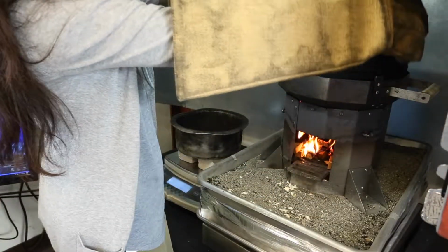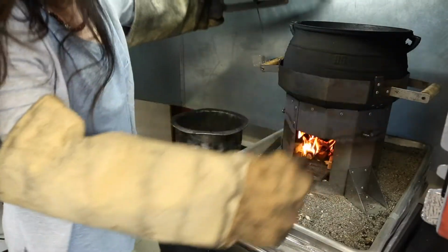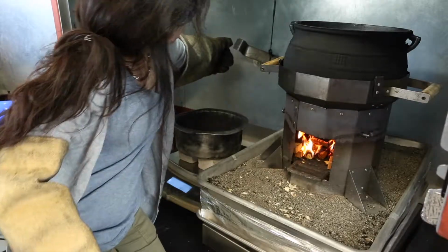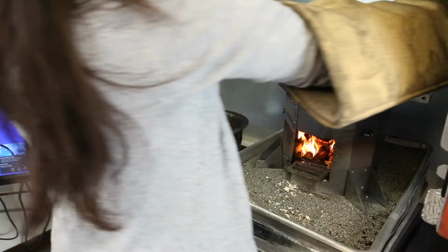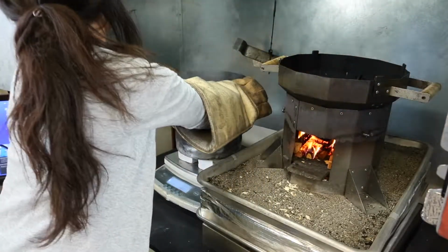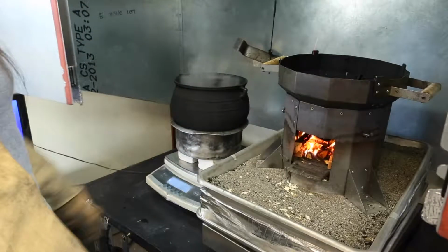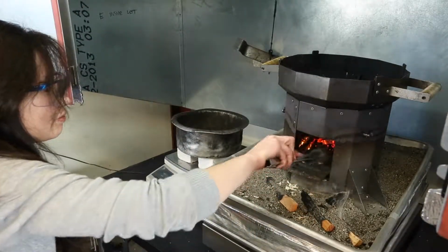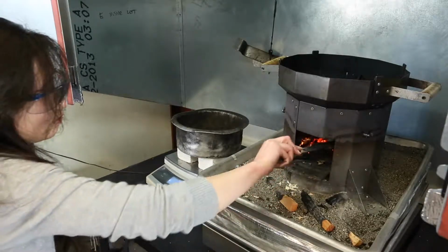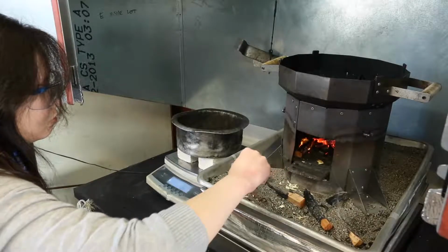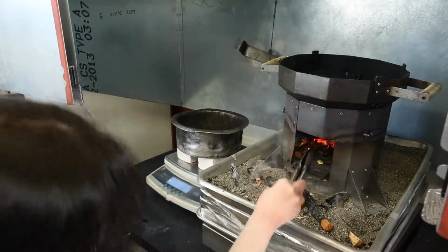We insulate the scale from the hot pot and fuel with 2 cinder blocks. We will then proceed to remove the pot of water, the unburned wood, and the char from the stove in order to weigh them on the adjacent scale. We remove the pot of water and weigh it on the adjacent scale. Afterwards, we put out the flames of the fire in preparation for separating the unburned wood from the char. We use sand to quench the flames because with water, there's always the danger of applying too much and thus contaminating the subsequent weight measurements.